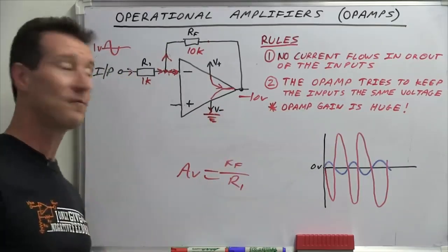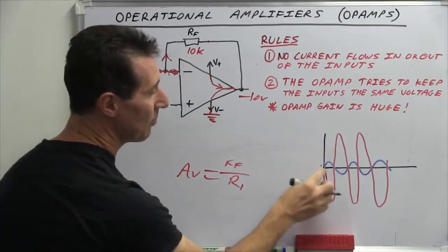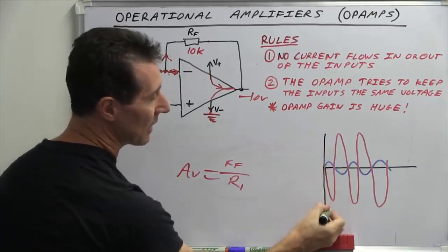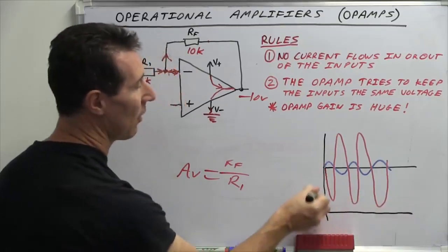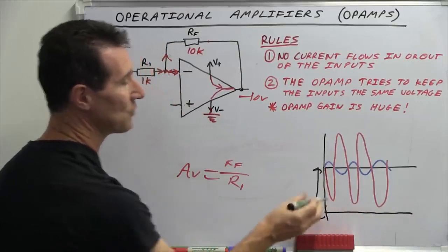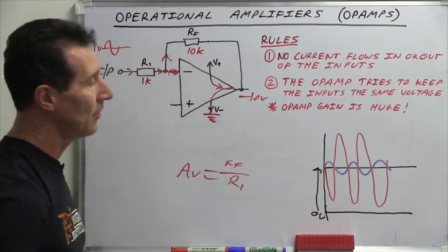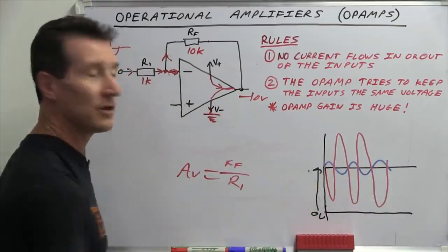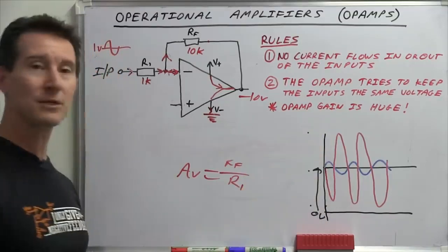But you still want to amplify your signal cleanly. Well, what we need to do is this 0 point needs to go right down the bottom here. So we need to offset. If that's 0 volts, we need to offset our input and output reference by a certain amount of voltage. How much? Well, typically half of your supply rail to maximize your headroom.